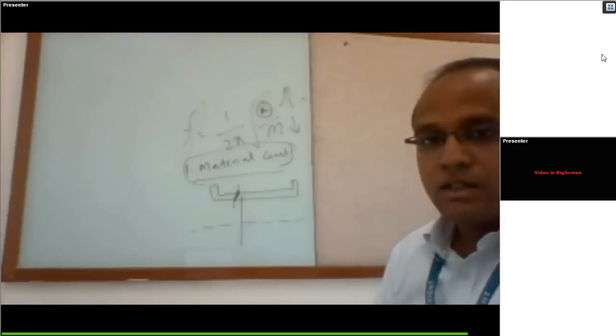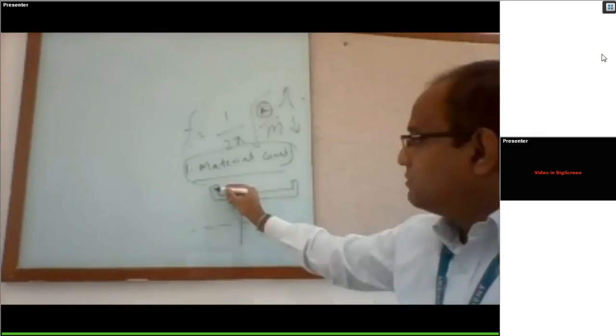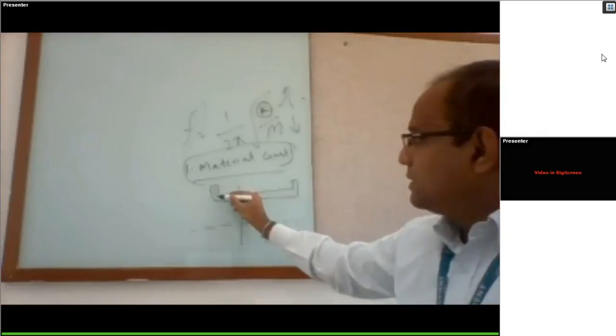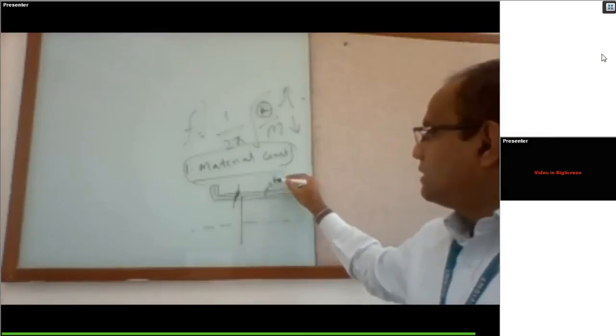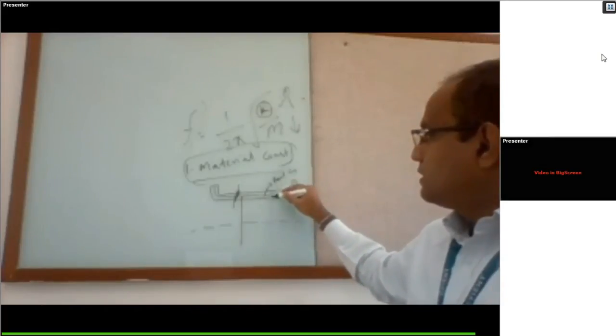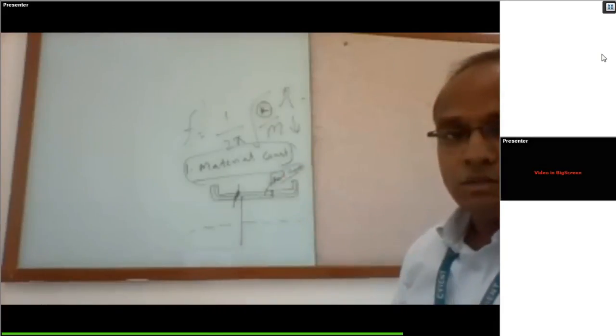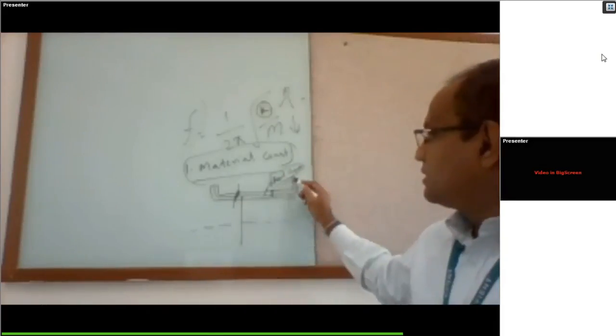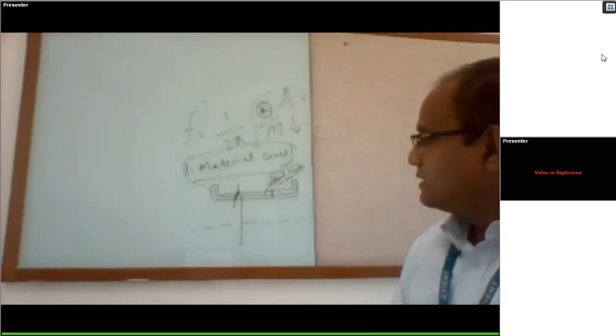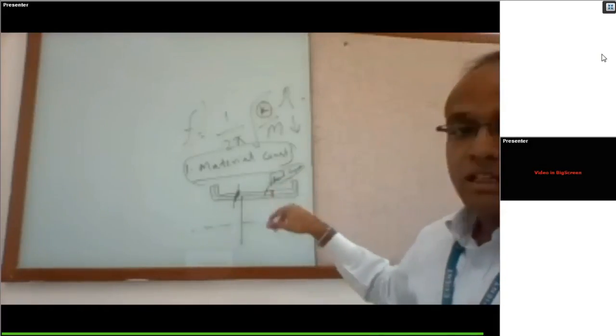In a shell model it is very easy to run several design iterations. The reason is that the mesh is there and the thickness is assigned as a real constant. So we won't disturb the mesh, but we will be playing with the real constant. I did several iterations by changing real constants.